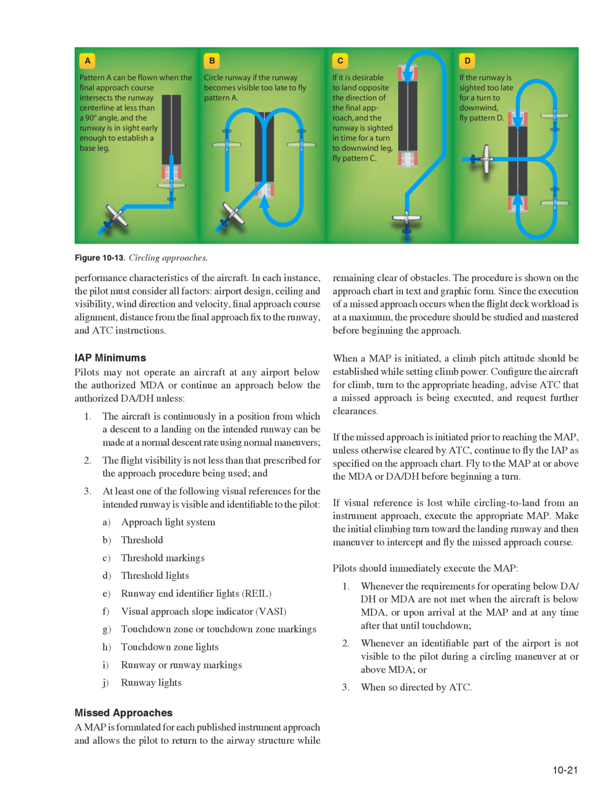Performance characteristics of the aircraft. In each instance, the pilot must consider all factors: airport design, ceiling and visibility, wind direction and velocity, final approach course alignment, distance from the final approach fix to the runway, and ATC instructions.